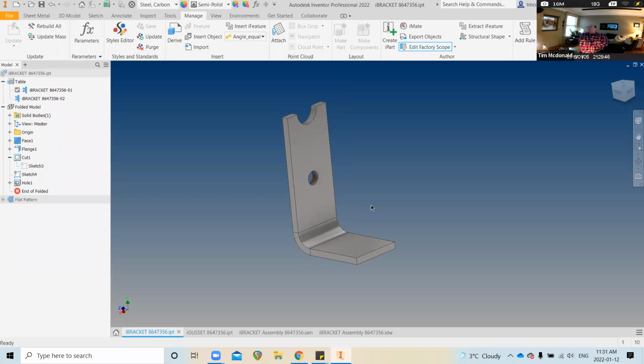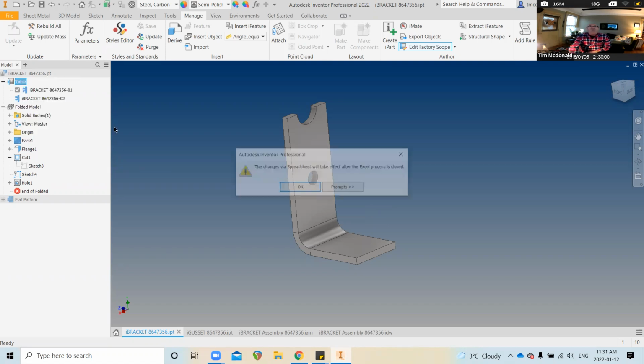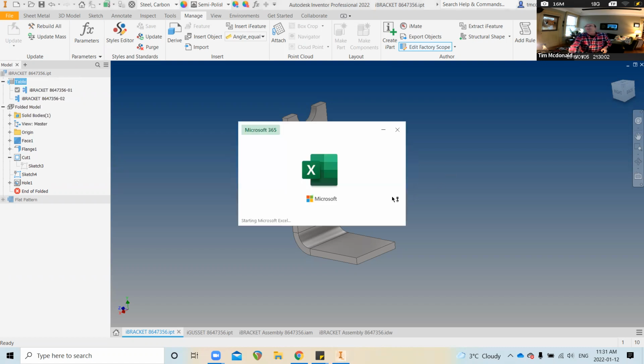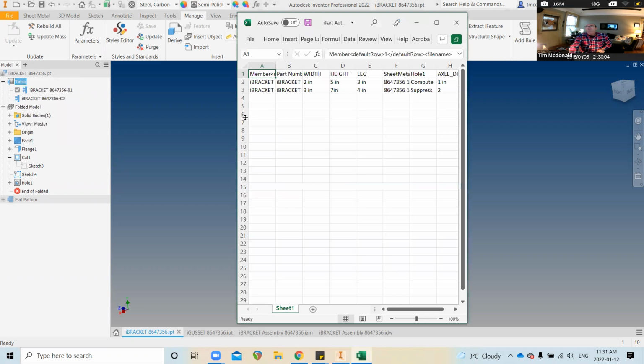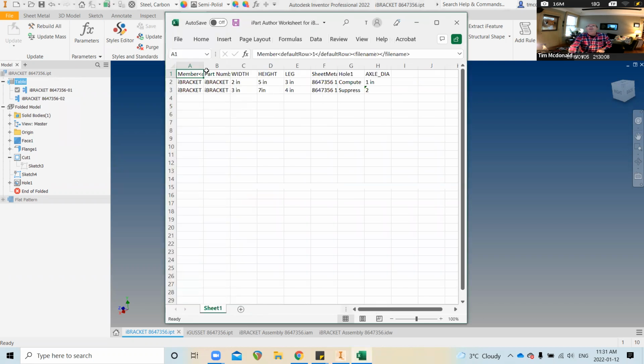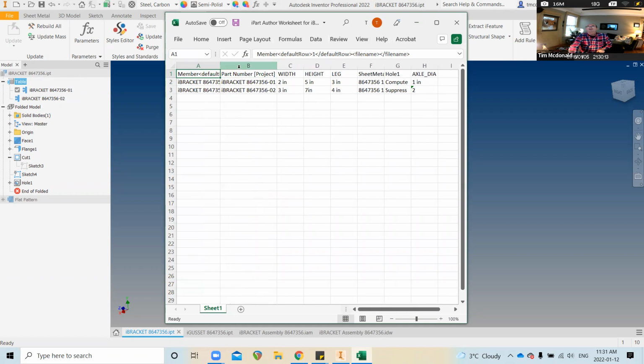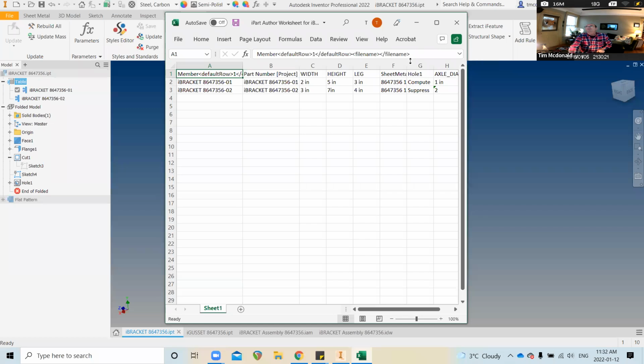And you know what, I never even touched on creating an Excel sheet to control these components. But this is all so easily done if we edit our table as a spreadsheet. And if we were to make changes to our drawings at this point now, then they will update as soon as we close this sheet. So I could modify the values in my Excel sheet, and they would update in the drawings after I close my Excel sheet.